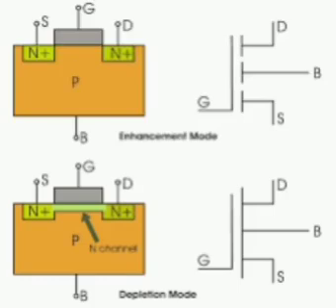The width of depletion region in unbiased condition is given by W equal to root of 2 epsilon V naught by Q into (1 by Na plus 1 by Nd). If you reverse bias the diode by voltage V, then in the formula of depletion width V naught is replaced by modulus of (V naught plus V).